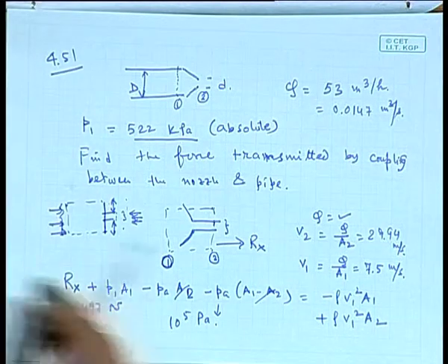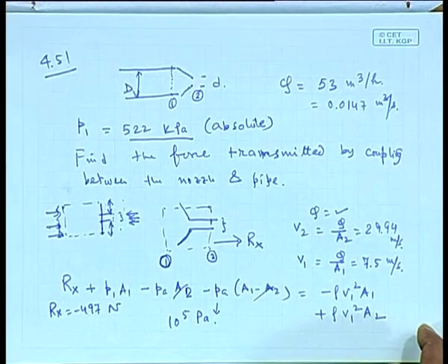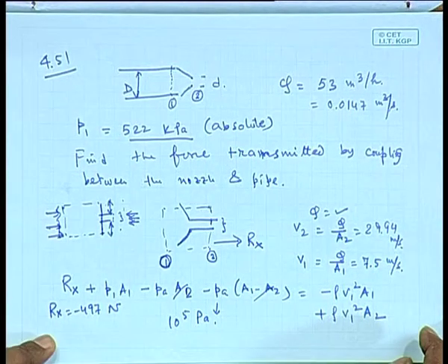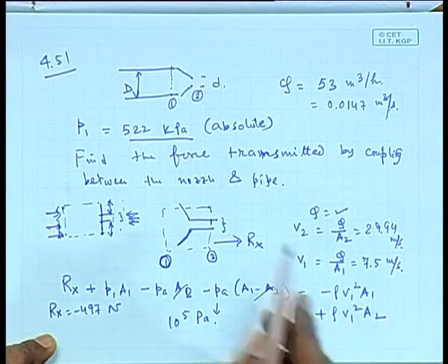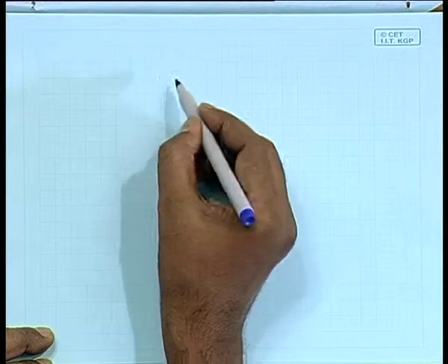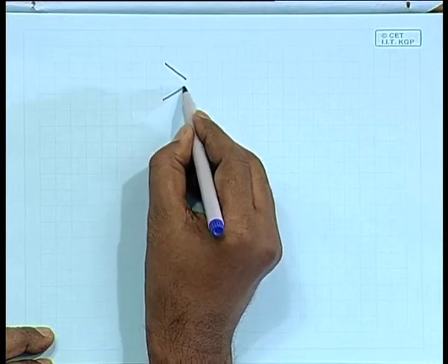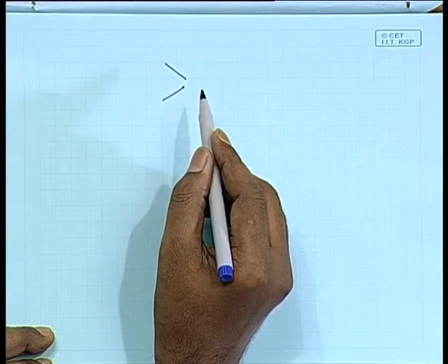Then I have an interesting problem on elbow. Say if we took the nozzle as a control volume, then sir, the area through which the atmospheric pressure is acting will get reduced. If I take the nozzle only as the control volume, rather than taking a box like control volume. Let us see. Only nozzle. Okay.